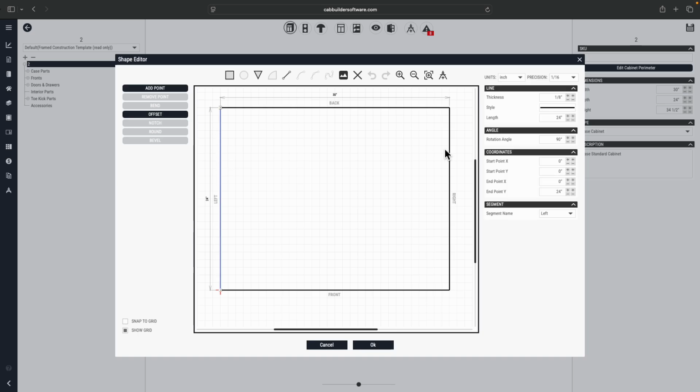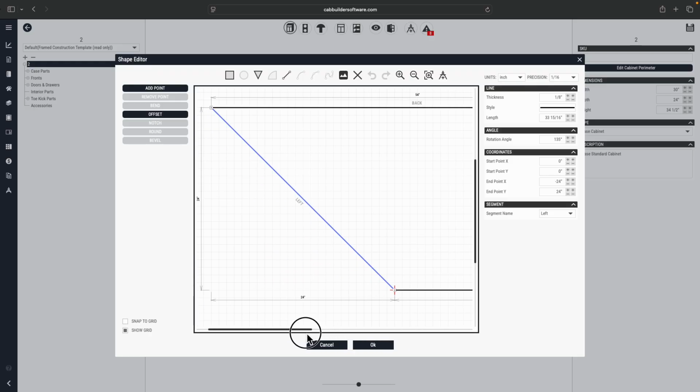left segment. And looking to the coordinates of that left point, which would be, let's see, the start endpoint will be 0, 0. That's this endpoint here. Endpoint is 0, 24. So I'll just subtract 24 from that x coordinate, making the shape that I'm looking for.